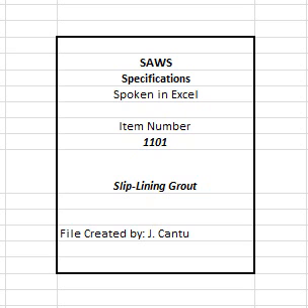Minimum penetration resistance after 24 hours shall be 100 psi, in accordance with ASTM C403/C403M-08. The minimum compressive strength at 28 days shall be 300 psi in accordance with ASTM C495/C495M-12. Grout mix shall have less than 1% shrinkage by volume.